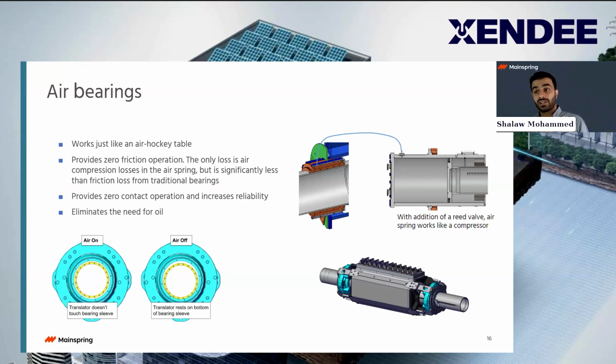Again, these air bearings actually increase the efficiency for us. First of all, the reaction itself is a low temperature reaction, so we don't need to take heat away from the system. This is an air cooled system, not a liquid cooled system, so we don't need to deal with a lot of heat taken away. Also, we don't have any valves. It's just slots open for intake air and exhaust air. And we don't have any oil. If you look at an engine, literally half of it, probably more than half, 60% of it, is just auxiliary load to manage the oil and the airflow and so forth. We don't have any of those issues. That's why these air bearings are a huge attribute of our technology.